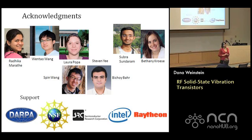I have a question about bulk CMOS resonators. Do you have any characterization data on how much of resonance power leaks through the bulk of the CMOS? Because when you see the clocking circuits like PLL and other circuits, the substrate noise is a major bottleneck there. Well, the first measurements on bulk CMOS were done this weekend, so we don't have that data yet.